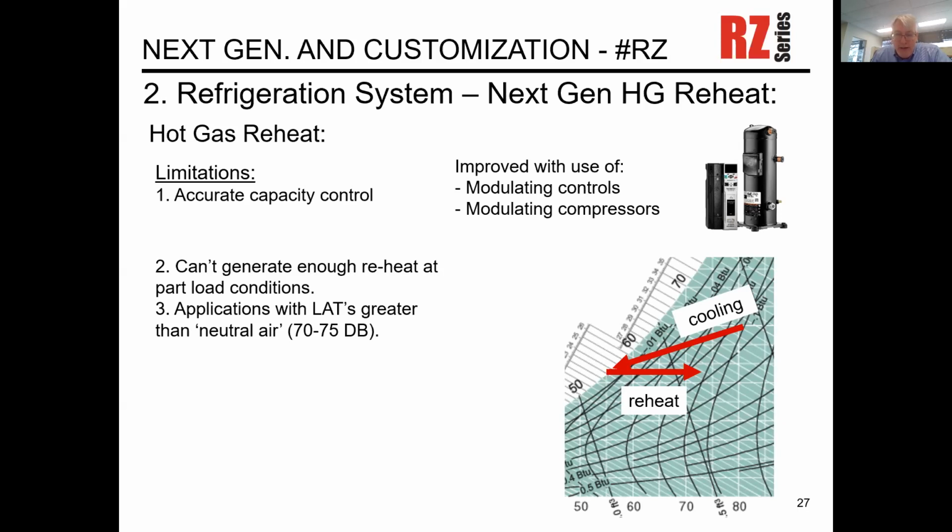You have your cooling system starting at 80/67. You're running through your cooling coil down to about 55. And then you have a second reheat coil that reheats the air sensibly from 55 up to about 70 or 75. Now, when you have part load, just realize that part load cooling means your mixed air temperature entering is not at 80/67. It's somewhere much closer to that 55.